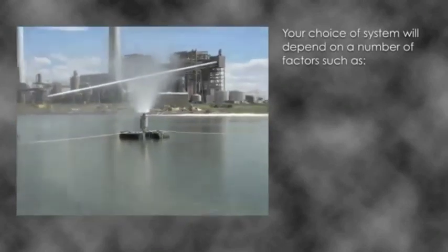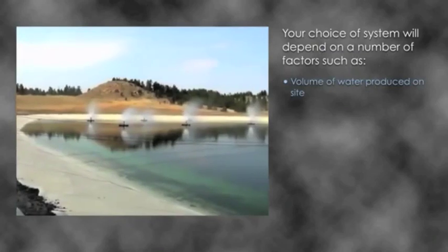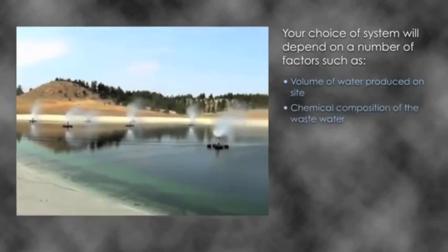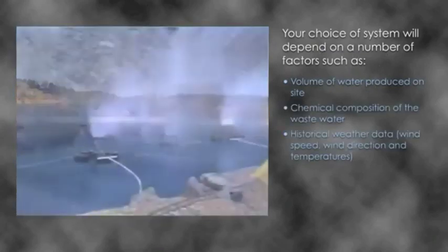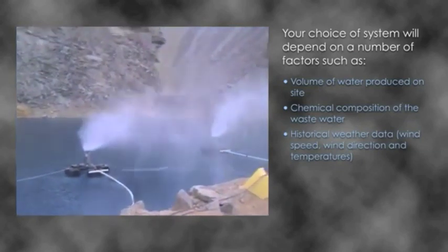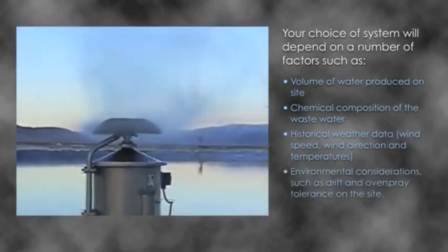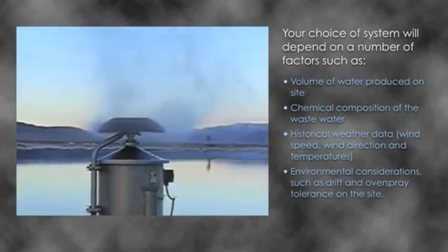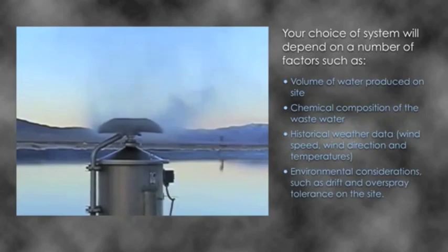Your choice of system will depend on a number of factors such as volume of water produced on site, chemical composition of the wastewater, historical weather data, wind speed, wind direction and temperatures, environmental considerations such as drift and overspray tolerance on the site.